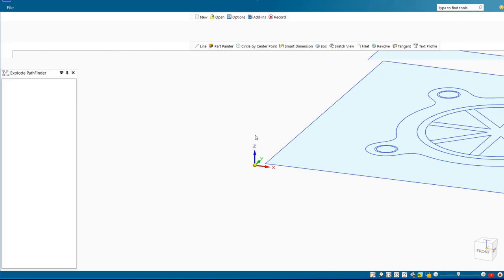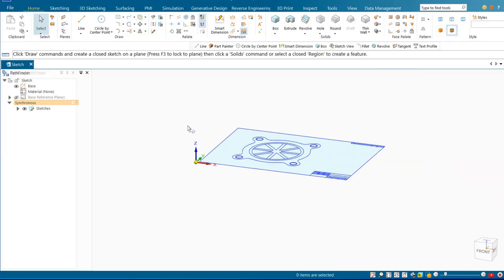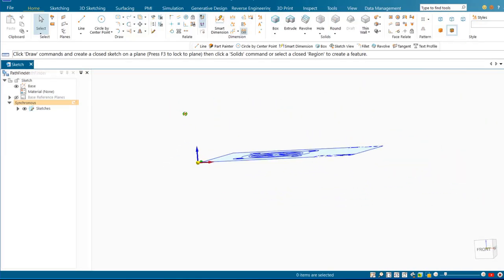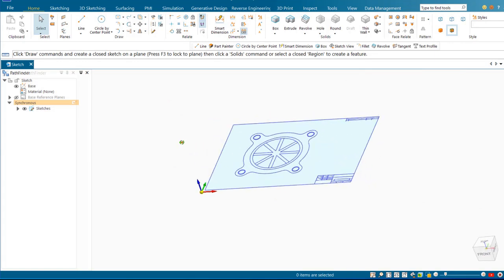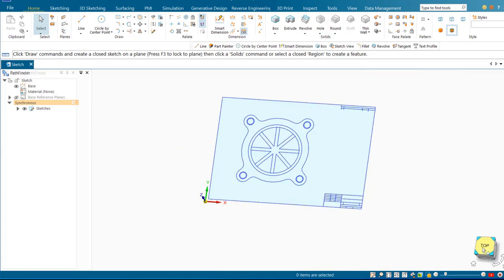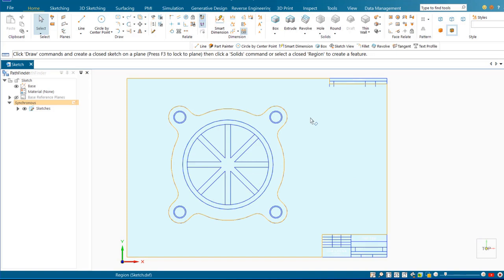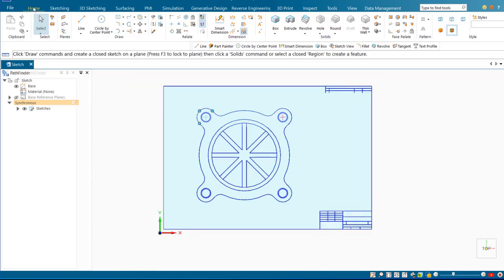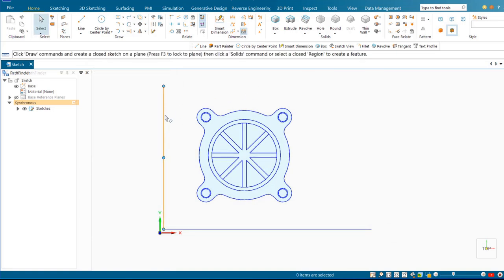Okay. There's the DXF file. You can see it's just like a piece of paper. So what I might do first is just come and look at that from a top view and come back to select. I'm going to get rid of all this AutoCAD information. I don't want all this sheet. So I'll hit delete. Then I could just delete these other lines also.